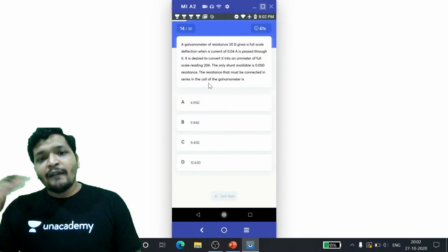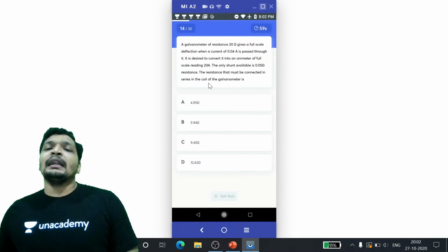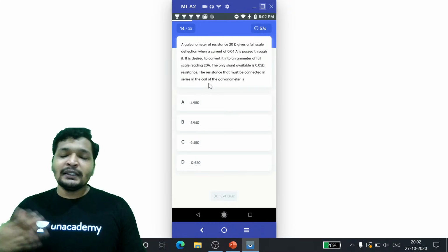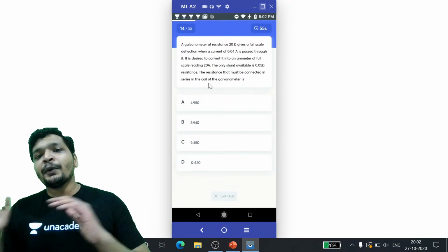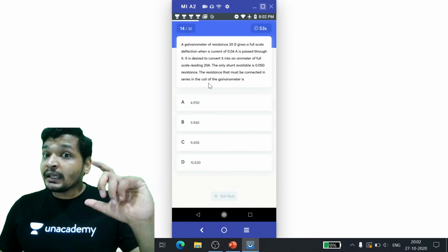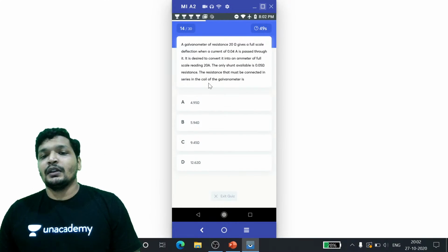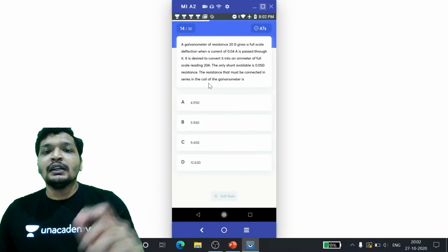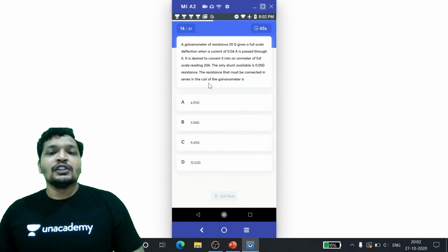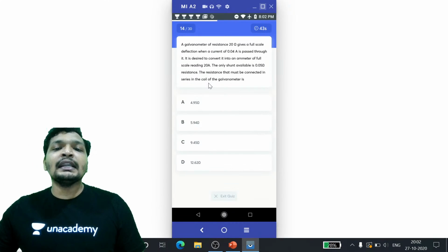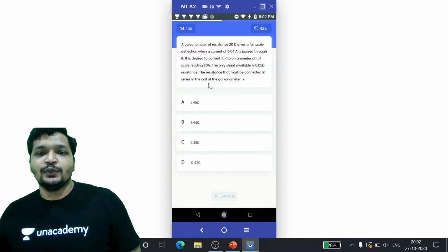So it's going to be V naught divided by 3L by 2, so it's going to be 2 V naught by 3L. Now this is the new potential gradient. But the secondary cell's EMF is constant, which was found out to be V naught by 3. So where will you find the V naught by 3? At L by 2, right?